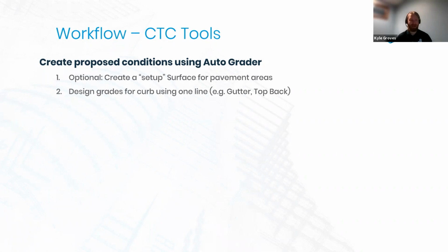Now, I'm not going to walk through how to set this up, but I will show that I am using this concept of a setup or a molding grid surface to inform some of these complicated horizontal pieces of geometry. But once I've got a design that works in my pavement area, then I can create those stepped offsets to come up with my curb configuration, or to come up with my detention basin, safety shelf configuration, slopes, all that stuff.